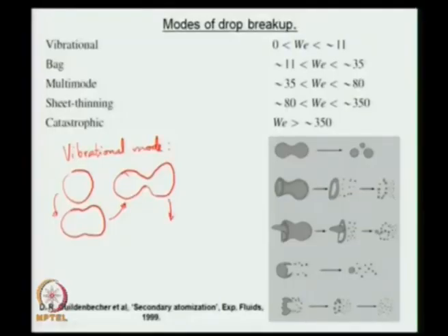So, in other words, I may have this vibration initially small, but because the air is feeding energy into this vibrating drop, this amplitude of the vibration could increase, and one could imagine very simplistically that if the amplitude of vibration becomes on the order of the radius of the drop, then you have a situation where from here you come to something that looks like that and it could pinch off.